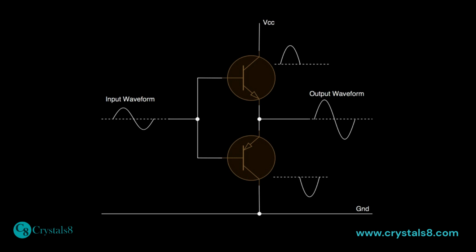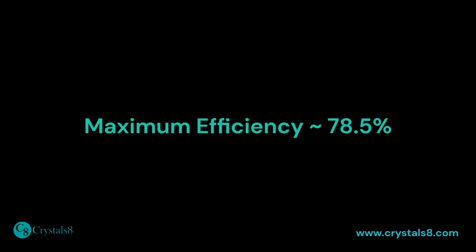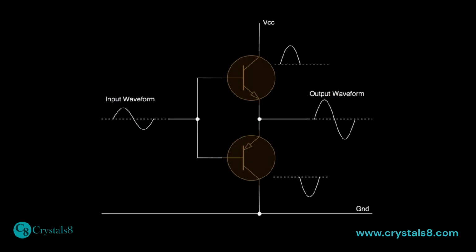Class B amplifier performance is vastly increased over Class A amplifiers due to the two transistor setup. This type can achieve 78.5% of maximum theoretical efficiency. These power amplifiers are found in battery-operated systems like FM radios. Since two waveform halves are superimposed, there is a dead band forming due to the base emitter voltages of each transistor. This is the major drawback of this type of power amplifier.